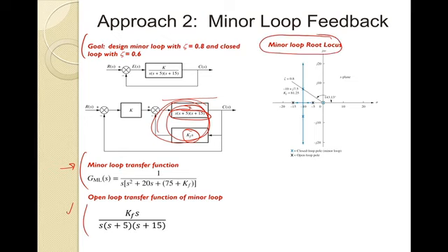And when we look at this, notice the following. We have a pole and a 0, both at 0 here. So those essentially look to cancel relative to the open loop characteristic. And then we have the two open loop poles here, one at -5, one at -15.